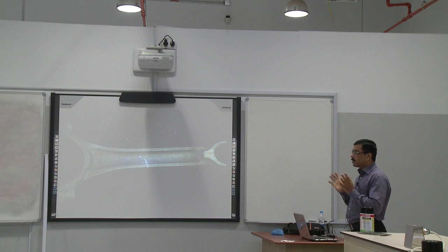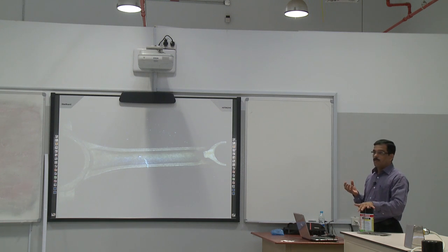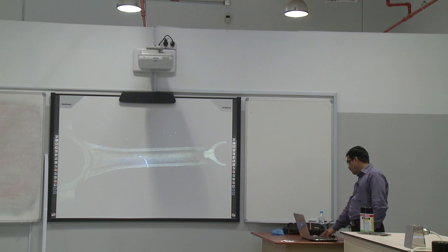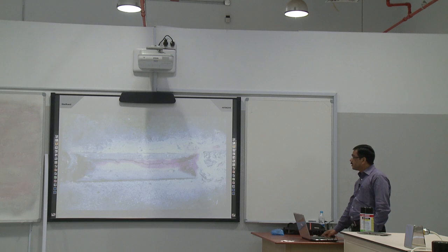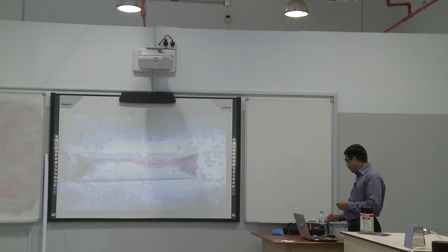So these are the basic theory about penetrant testing. It is not much complicated. It is a very simple process, and not too much technical skill is required. The main advantage is that we can use it in any area, because magnetic particle testing cannot be used if there is no electricity. But penetrant testing we can use in any remote area, whether electricity is available or not. So that is the simple method we can use. Like visible cracks, open cracks, we can find out.